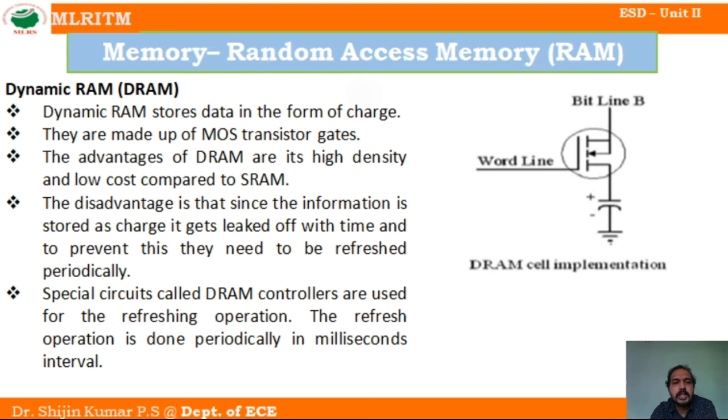Special circuits like dynamic RAM controllers are used for the refreshing operation. This refreshing operation is done periodically at millisecond intervals. Every few milliseconds we have to refresh. So that is the disadvantage of DRAM.